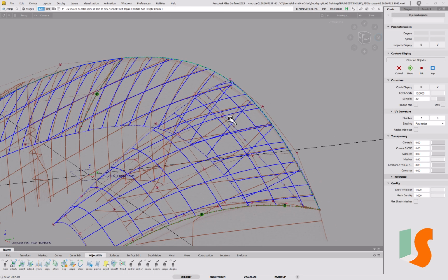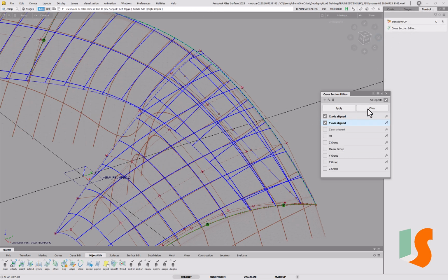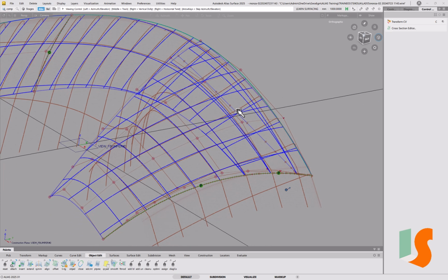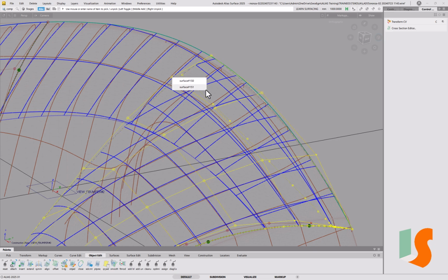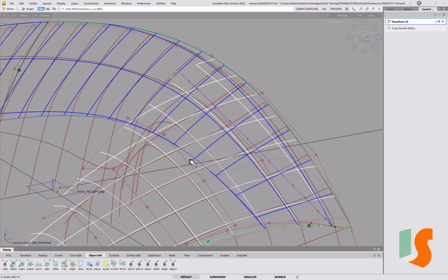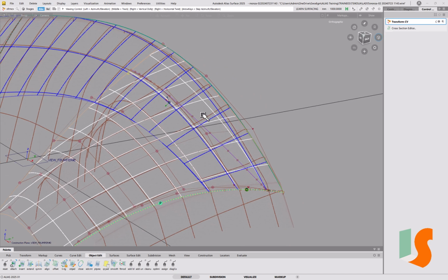But maybe we can obviously affect this intersect with this surface as well. Now we are very close to that data, although that's difficult to make out with these sections because they've not updated properly. So let's bring those back on. So around here we're close to that data. Up here this surface actually disappears completely, and so there's some freedom to move these points around. As long as we don't affect these sections too much, we can do that, and certainly the top edge, and that will help that intersect there. Something like that. This point could also be moved if it's going to help.